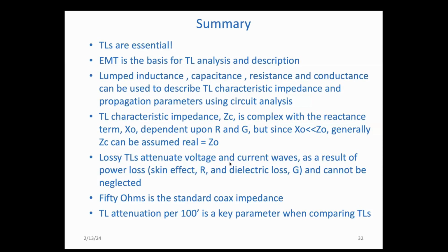Yes, to be exact, the characteristic impedance is complex. However, the reactance term is small enough that we can consider it real. And the reactance term is dependent upon R and G. And if R and G are zero, as we said before, then the characteristic impedance would be real. R and G do affect the loss on the line, and we can't neglect them.